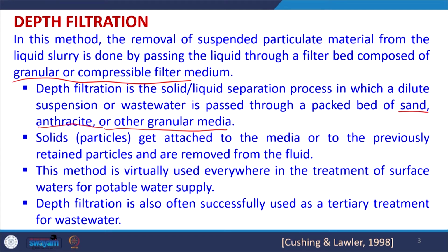During this filtration the solid particles get attached to the media or to the previously retained particles themselves. In the starting they will be retained by the media, but after some time some cake deposition will occur. So, the previously retained particles will also filter the much smaller particles which are coming now.